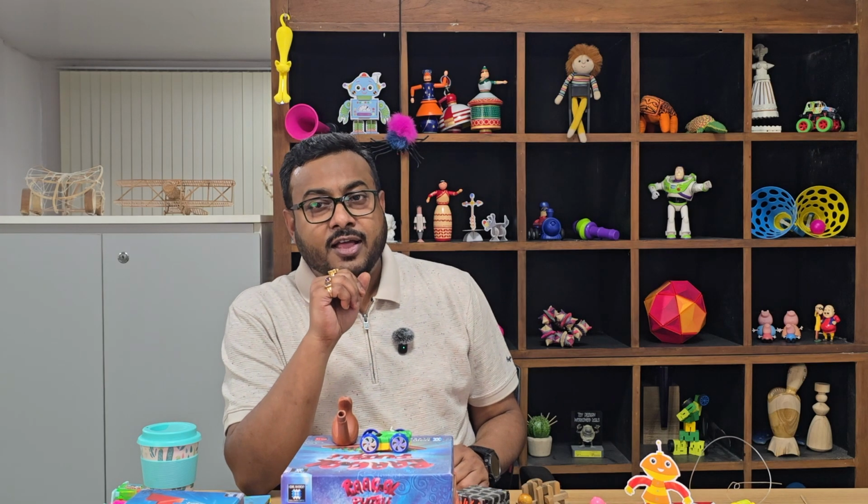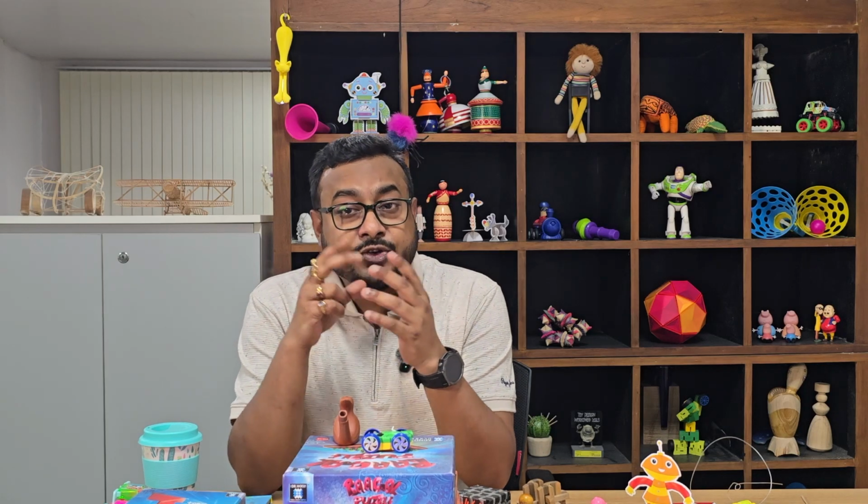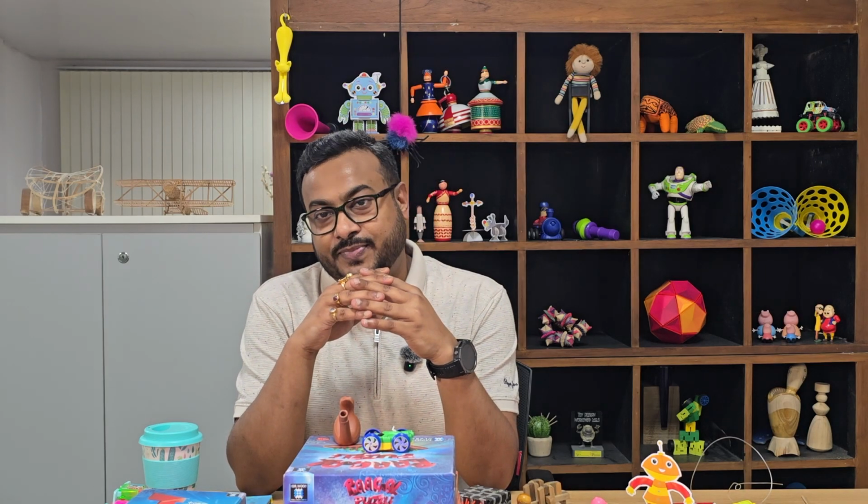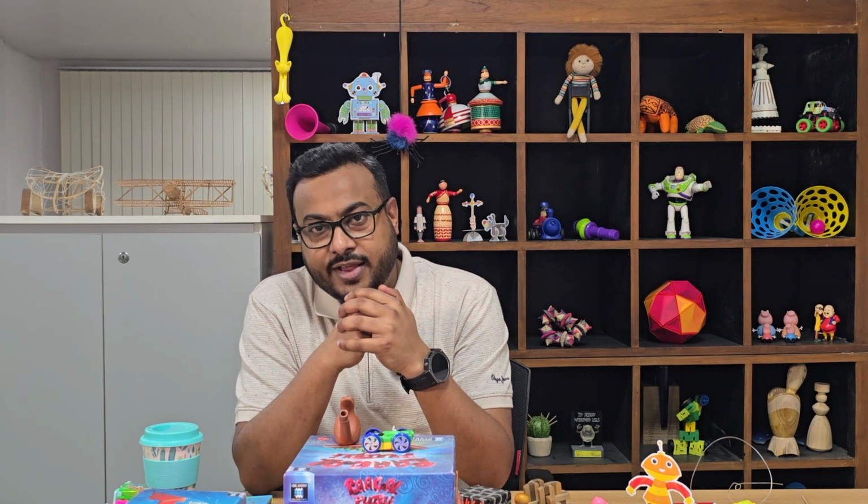To achieve good ergonomics in toys, you must follow these 3 steps. First, clearly define the age group. Second, use anthropometric data for that age range. Third, often design for a range, not just one extreme. Anthropometric data gives us measurable reference points.